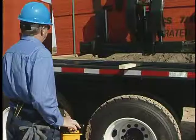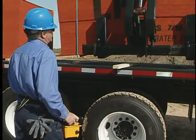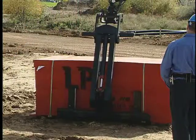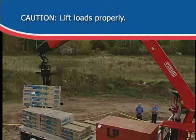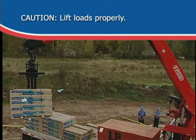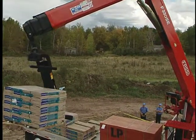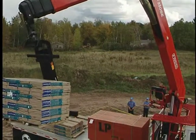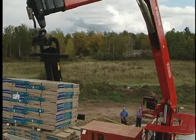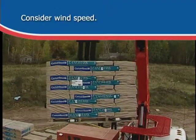If there is a problem, stop the lift immediately and get the load to the surface, whether the truck bed or the ground. Lift loads properly. Lower, raise, brake, and swing slowly. Don't change speed suddenly. If a load is moving too fast, it tends to drift, causing instability. Consider wind speed and how it may affect work.